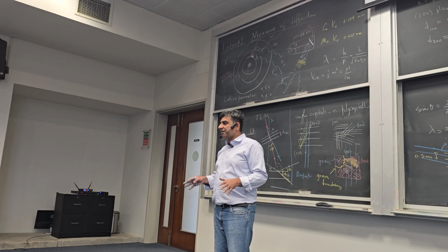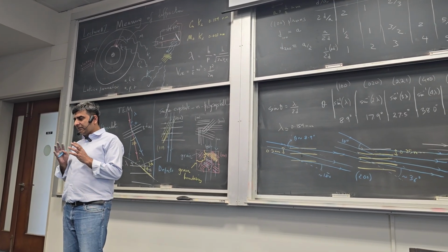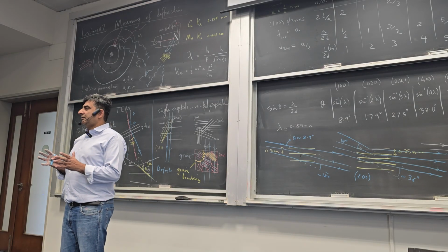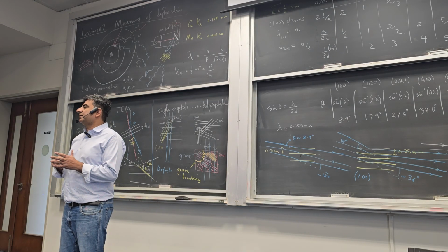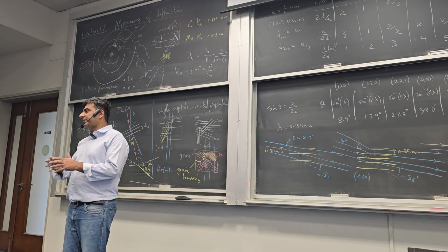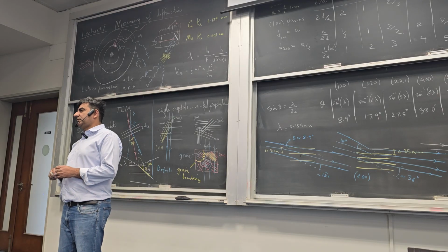So when you have a polycrystalline material and you are finding out some physical property of that bulk material, and if it's anisotropic, the anisotropy may get averaged out. Because all crystallites are available, all directions are possible, and when you're measuring something bulk, you get the average. Okay.